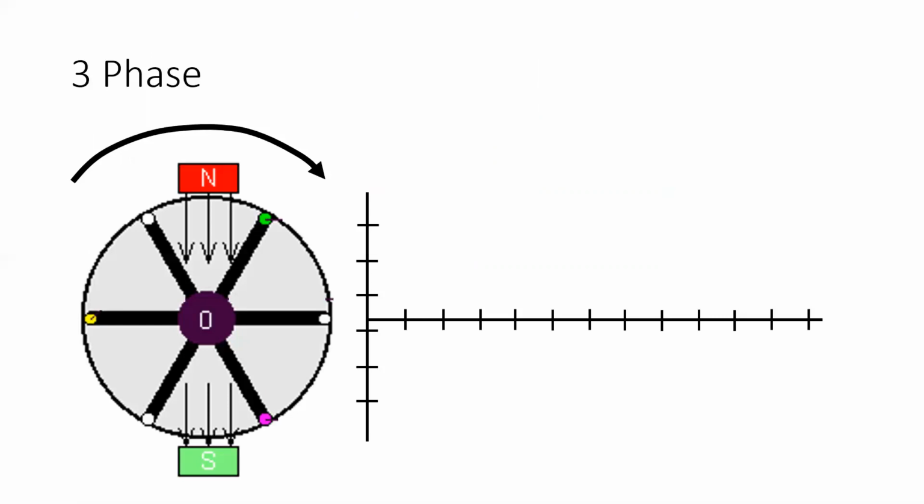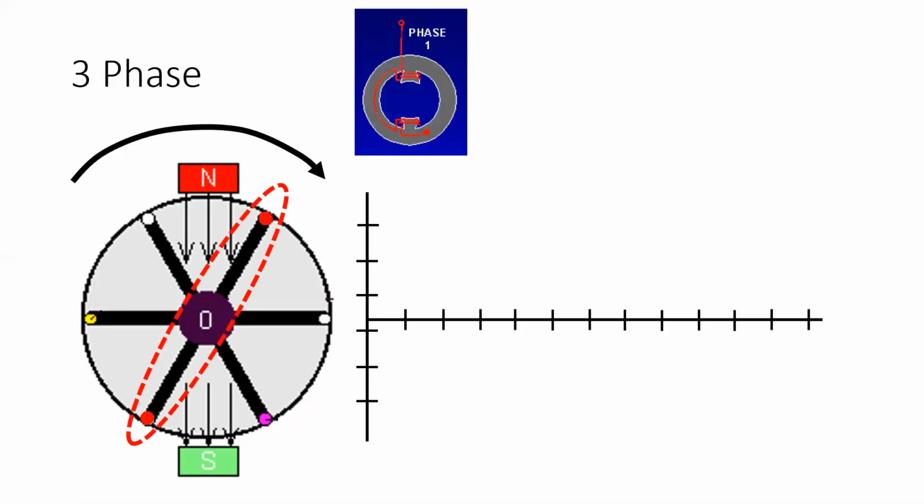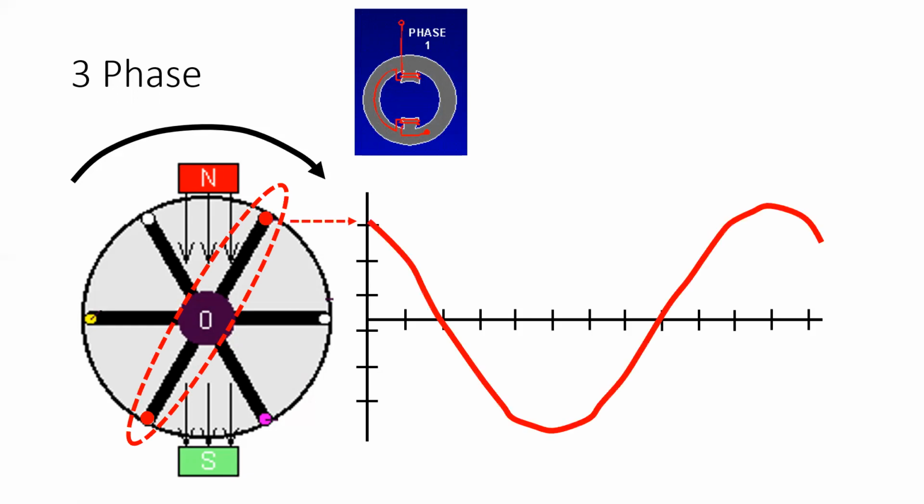If we look at a 3-phase generator, there are going to be 3 individual windings. And if we look at each one individually, we can then start seeing where the sine waves are being generated. If we look at A phase here, this would show that we have an independent voltage that's being generated on this one individual winding. Now, of course, there is no other winding that's going to reach its peak value at exactly the same point because no 2 windings will be passing the main face of the poles at exactly the same moment. There's a 120-degree separation between the windings.